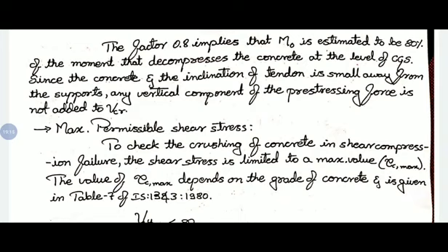Since the inclination of the tendon is small away from the supports, any vertical component of the pre-stressing force is not added to VCR.